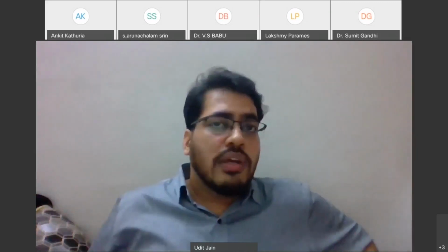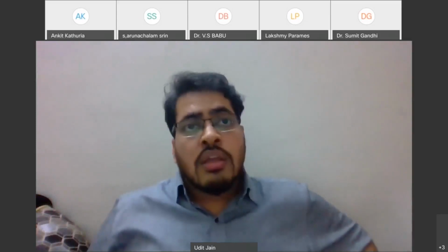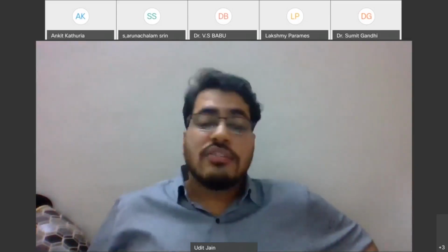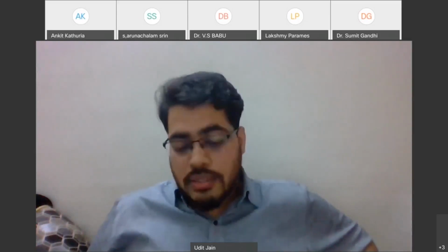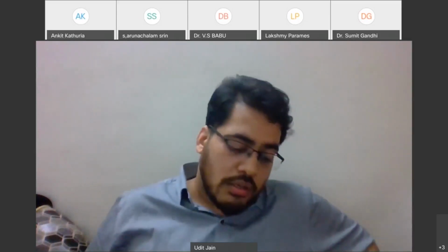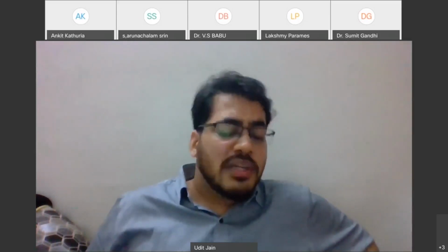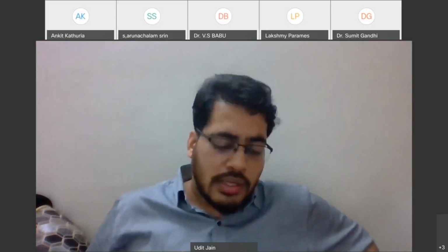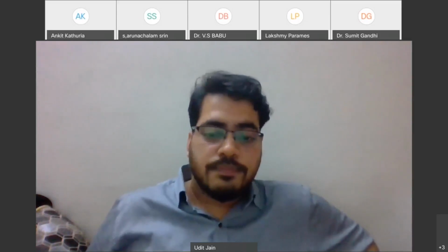So the basic heuristics are that if the PCU value is up to 3,000, we can go for a roundabout. If it is up to 5,000, we can go for a signal, and beyond 10,000, we can go for a grade separated intersection. But these values are based on experience. The IRC code does not authenticate these values, but they are very commonly followed in transportation engineering practice all across the country.